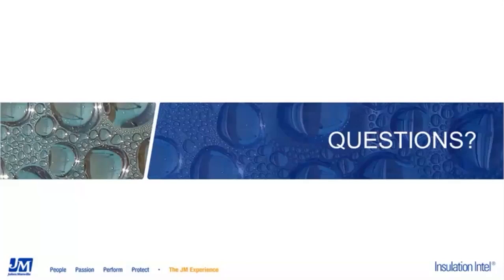So I would say that you want to try to insulate around it, vapor retard around it, and then seal around whatever the penetration is with caulking. Any kind of seal around a penetration is a weak point. And so again, it's best if you put a vapor stop or vapor dam on either side of these weak points. So if you have a valve, terminate your insulation on either side of it, and then insulate the valve.